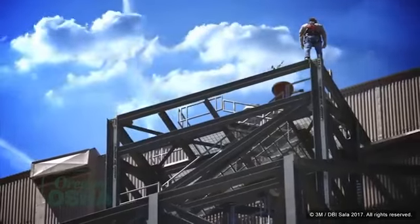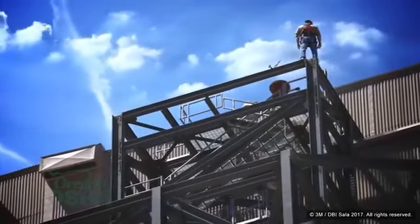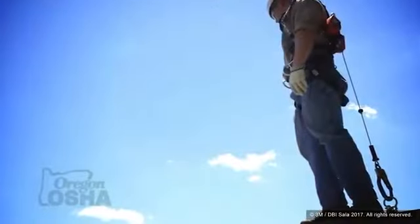If I'm an iron worker and I'm walking red iron tied off at foot level and I take a fall and strike an I-beam with my fall arrest equipment, I have a leading edge hazard, but I also have a sharp edge hazard where I need to make sure that I've identified that as a potential area where I could have a cut hazard. Our qualified people and our competent people need to be on the lookout for these hazards and making sure that workers are protecting themselves and using the right equipment that's there.